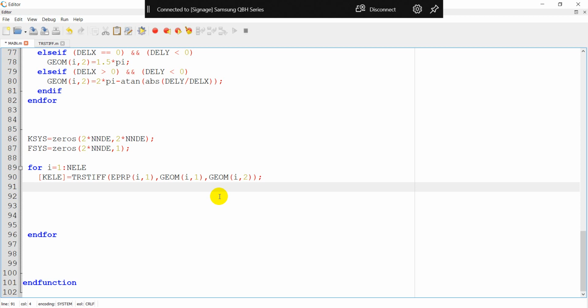Okay, well, let's see how the operation will look. We're going to need the for loop, of course, but you cannot use the i anymore. Now it's going to be the for j, okay? i will be out there, j equals 1 to 2. Why is it just 1 to 2? Why is it not just 1 to 4? It is 1 to 2 because you have 2 nodes for each element, and 1 node means 2 degrees of freedom.